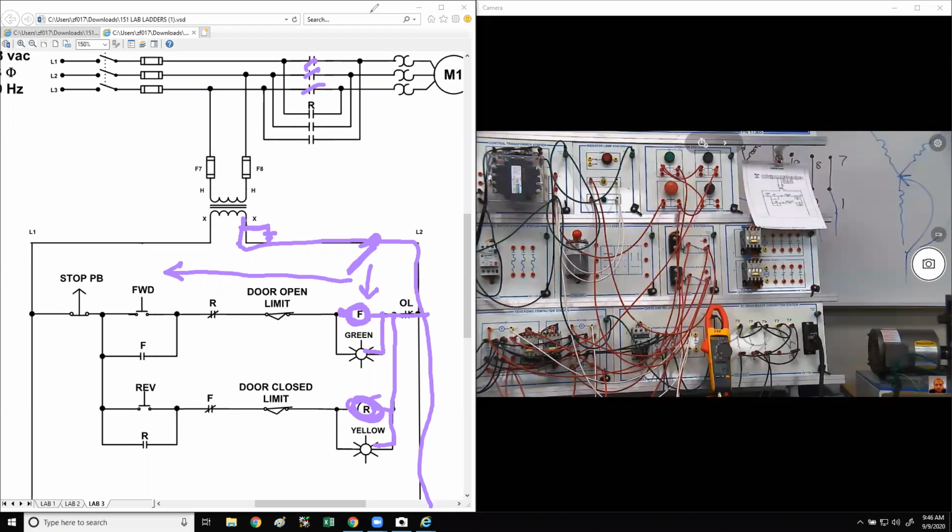Remember, one of those methods was isolate? You always want to isolate. So on this contactor, that is pin 21, 22, which is here and here. I would check continuity on there. It's normally closed, so it should always have continuity, unless the coil's pulled in.